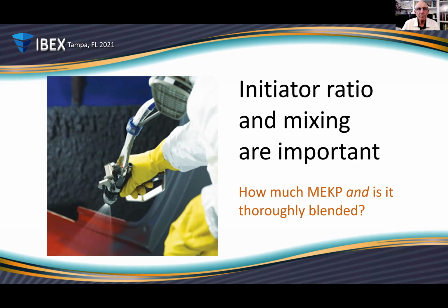We then have initiator ratio and mixing are important. How much initiator are you putting in the material? How much MEKP is it? And next, is it thoroughly blended? So we have two things going on here.